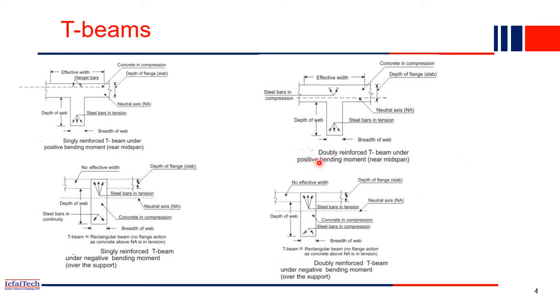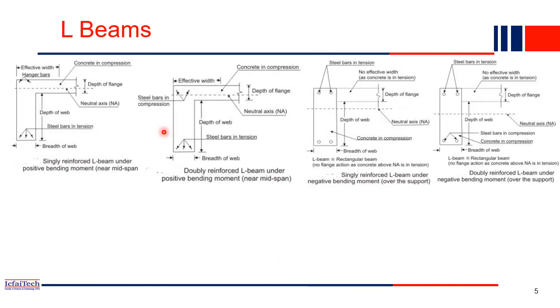So I'll just quickly go through this because you understood the main concept here. Now the corner beams are actually L-shaped. T-beams will be all the intermediate beams. For example, let me draw a plan. If this is a plan of a building, these are the different beams passing.